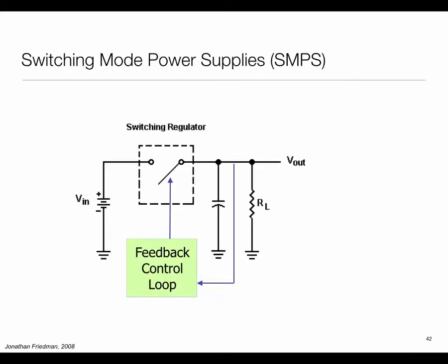So what you would usually see used in embedded systems are so-called switching mode power supplies. They achieve the same thing, except the control now goes into software effectively. The basic idea is that the voltage waveform I give to my load is a sampled version of it. Imagine I have this battery sitting out here, putting out a voltage of 5 volt. Through this switch, half the time the switch is on, half the time it is off. So the waveform out here would look like a square wave, which is 5 volt for half the time, and disconnected for the remaining half.